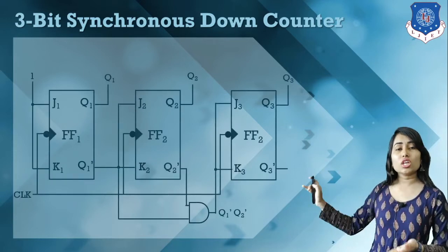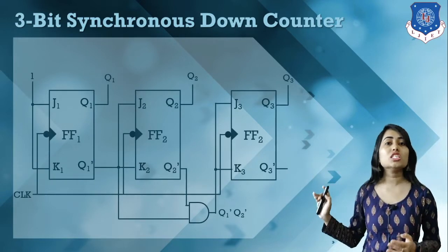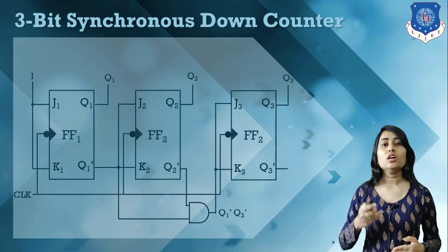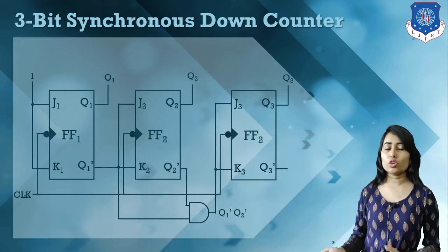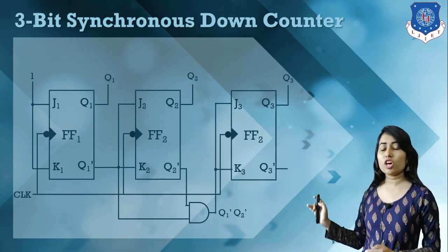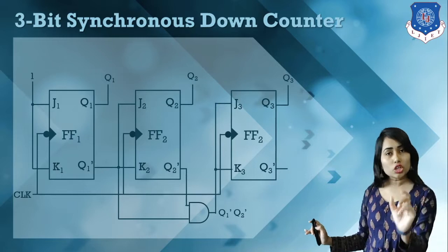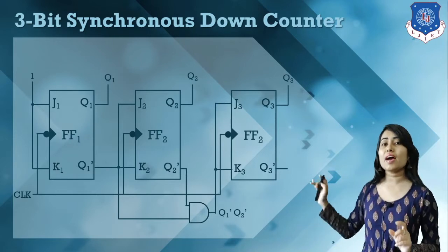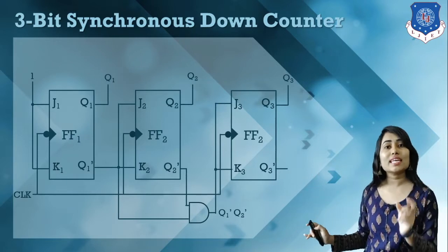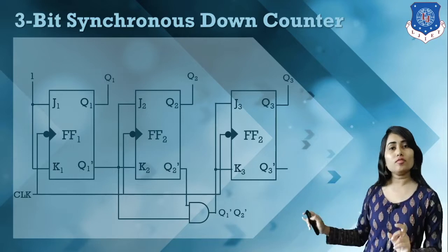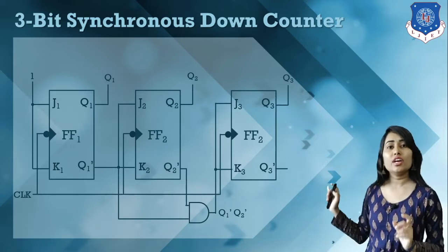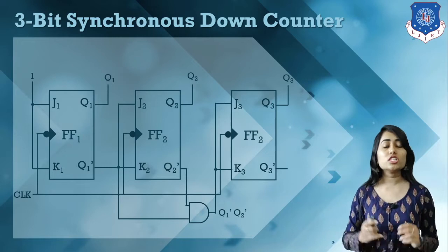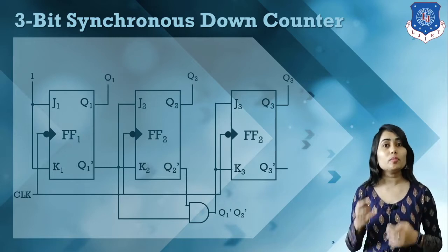Here, 3 flip-flops are used because we want to design a 3-bit synchronous down counter. As this is a synchronous counter, all flip-flops receive the same external clock signal. That means all flip-flops will work parallelly.